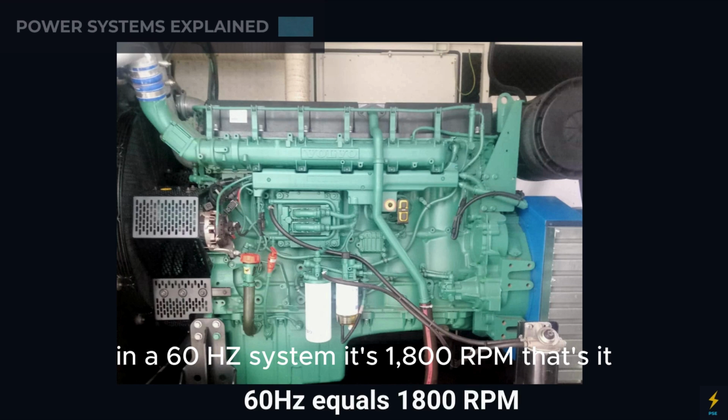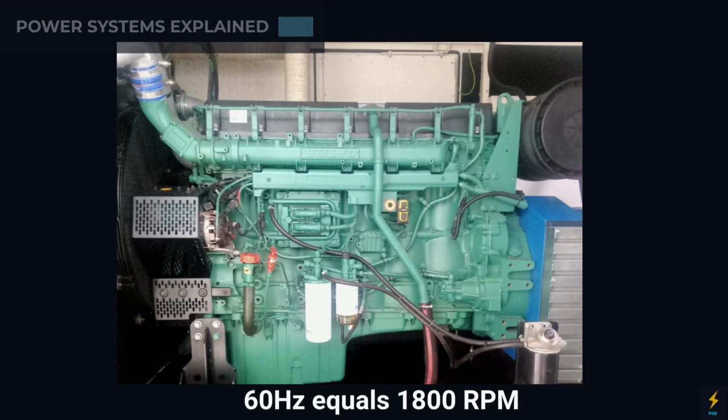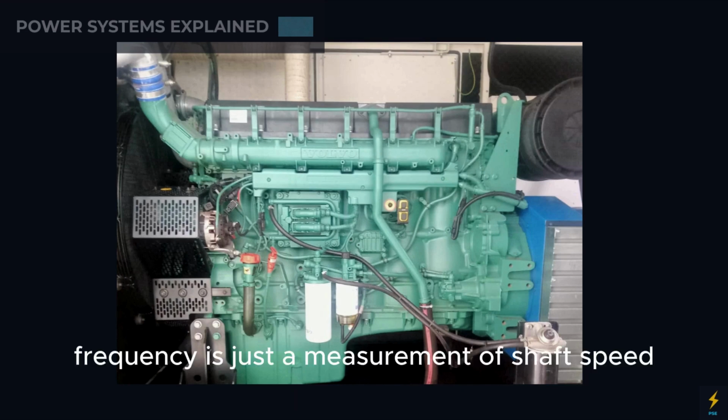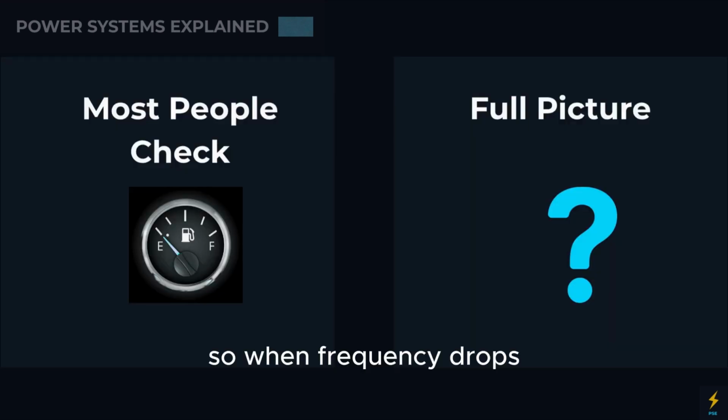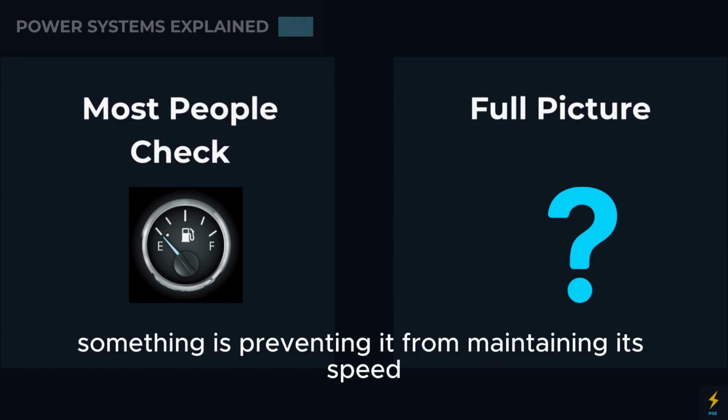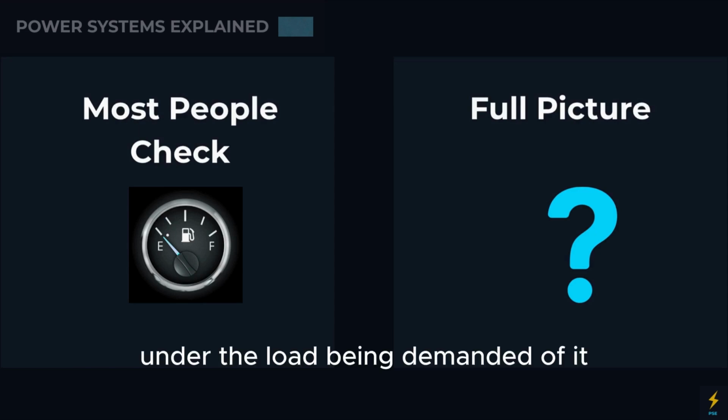In a 60 Hz system, it's 1800 RPM. That's it. Frequency is just a measurement of shaft speed. So when frequency drops, the engine is slowing down. Something is preventing it from maintaining its speed under the load being demanded of it.